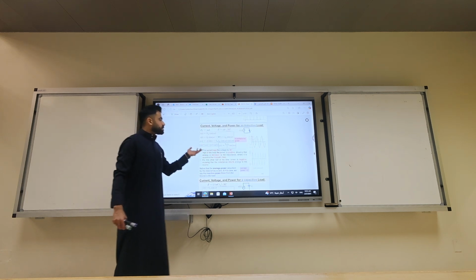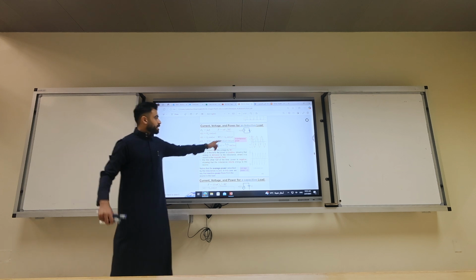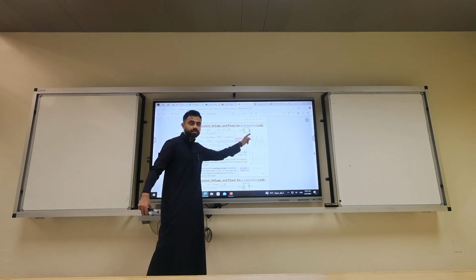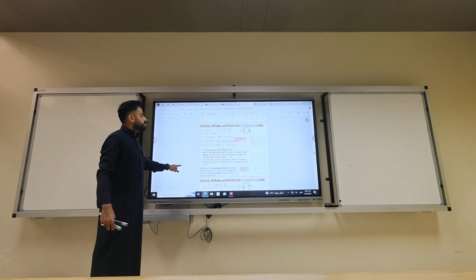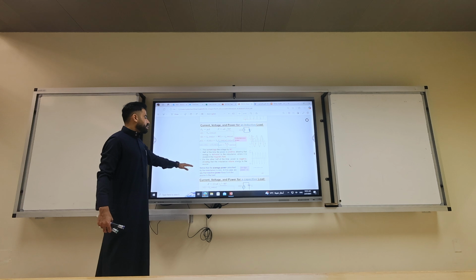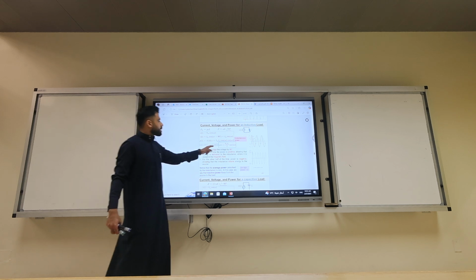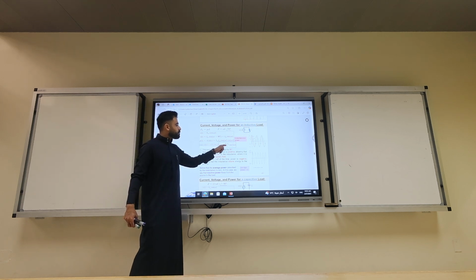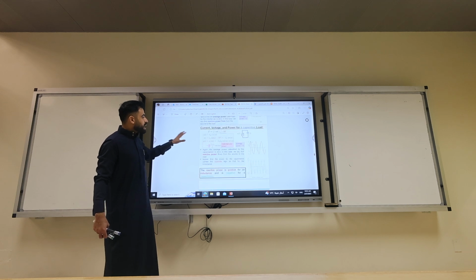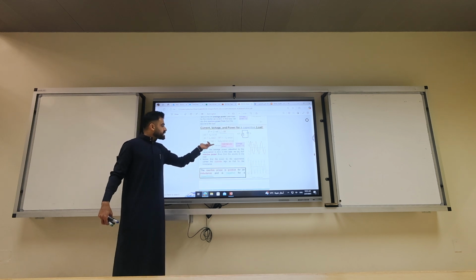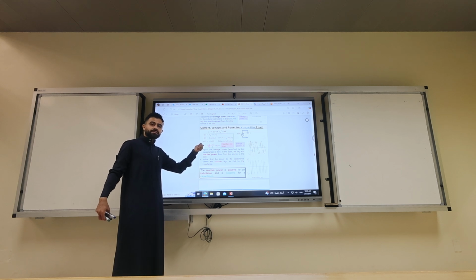For inductive loads, if you have only an inductor, like that circuit, always look at the circuit, you will have an average power of 0, and you will have a reactive power with the formula Vm Im over 2. This over 2 comes from the square root of 2 for Vm times the square root of 2 for Im. Get it? Then if we have a capacitive load, we will have the same reactive power, but it's negative.